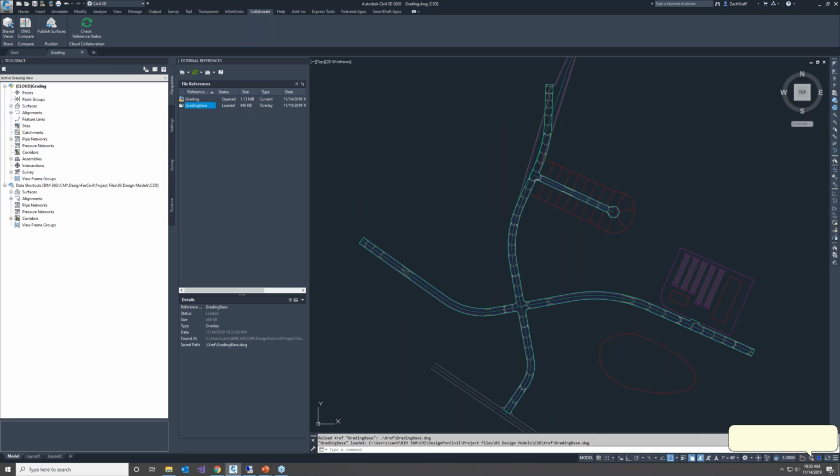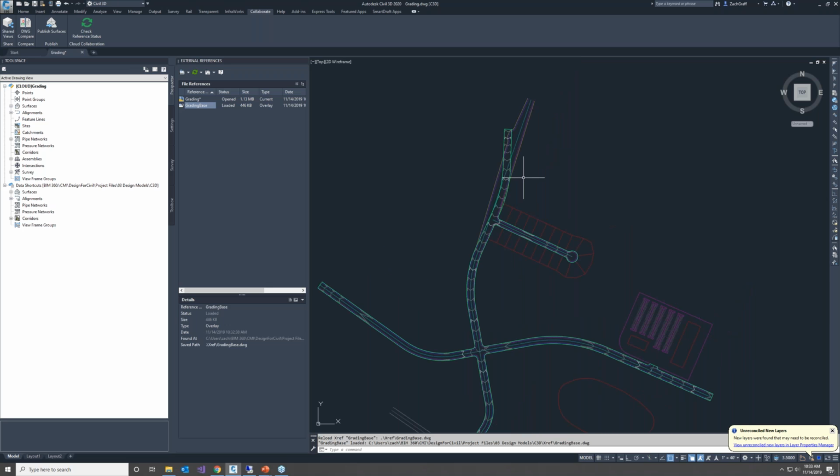Yeah, let's reload and see if it's come through. Yep, so not a very pretty modification, but you can see that process happened on a totally different computer in the cloud. We made a change to the file, and it's updated here. Same is true of my data shortcuts. So this really allows our entire Civil 3D project, data shortcuts, XREFs, and all, to reside there in the cloud.